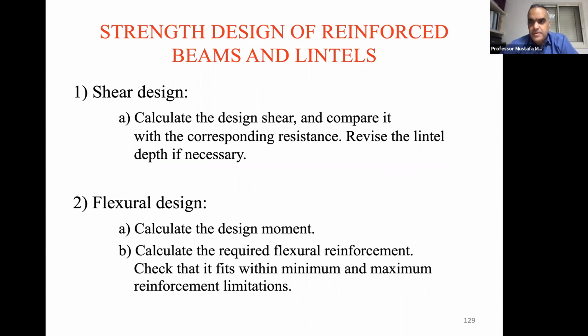Revise the lintel for the depth. So in lintel design, if we can avoid using reinforcement and use depth, so increase the depth, that is actually better. Because typically above openings, we have enough depth compared to the span of those openings. So we can check if the depth is enough for the shear resistance.